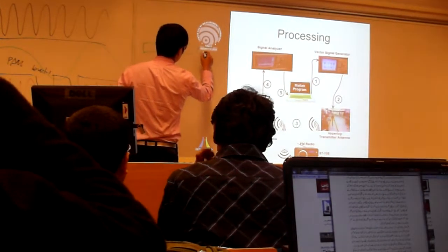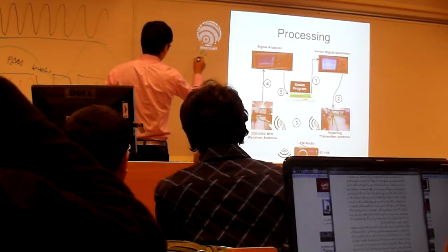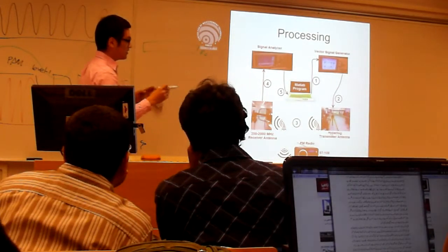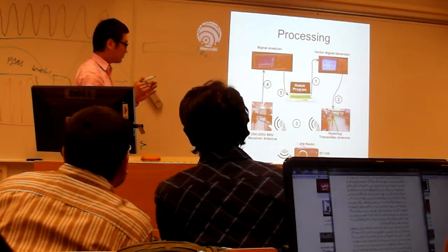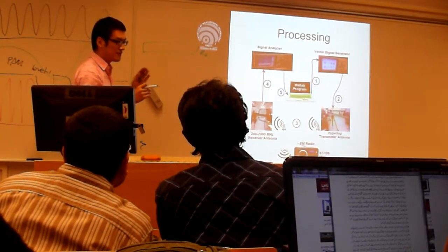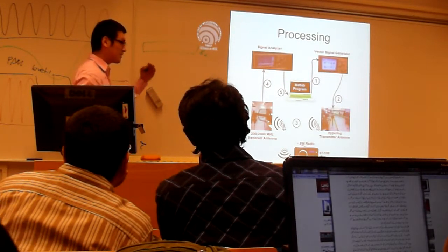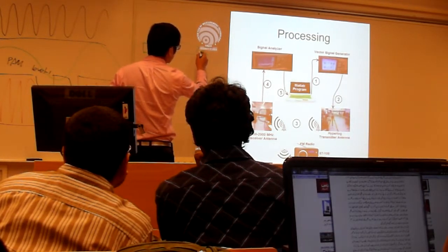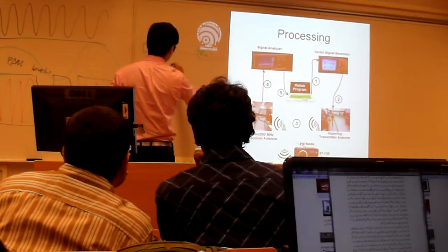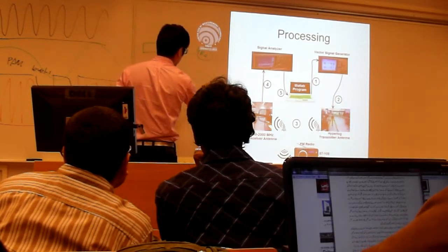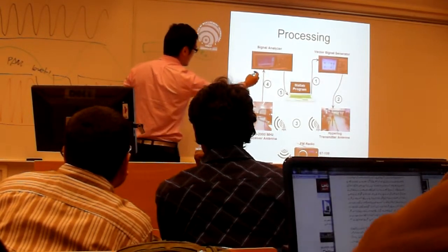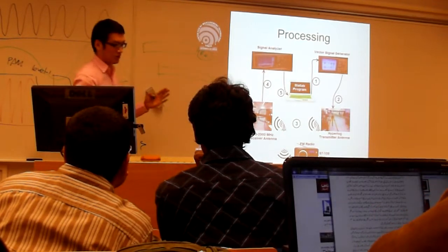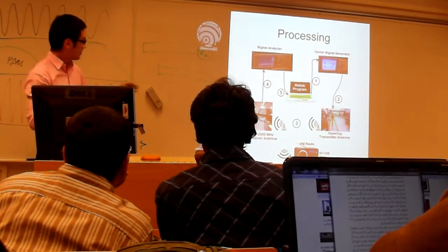And for example, this is our received message. For the synchronization, because we have time delay and phase delay, we need to know exactly the position where we start decoding, so that later we can match it to the original data. This is the receiving data, and this is the transmitting data, the original data, and we do the cross correlation between those two.